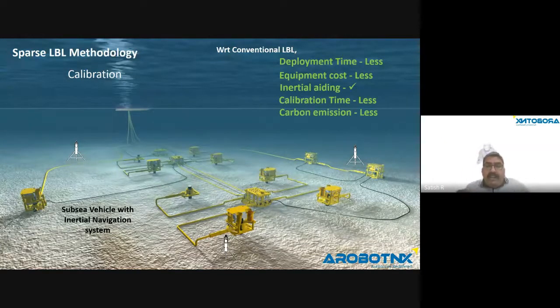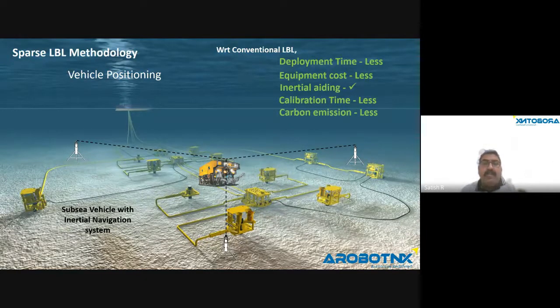There's no definite way of carrying out the 2D and 3D calibrations, it's still a lot of process. Even we have spent 2 years, we have got nearly many methods to carry out the calibration, but we're only highlighting the one most used in the industry. The biggest advantage of this one is when you carry out the vehicle positioning, you're going to run with only 3 transponders and a powerful INS Kalman filter model, and you are going to carry out the operation wherever it is. And you should also see the latest slide, I'll show you the ranges. It's not going to be like this, it's going to be far. It's going to be at least more than 1 kilometer.